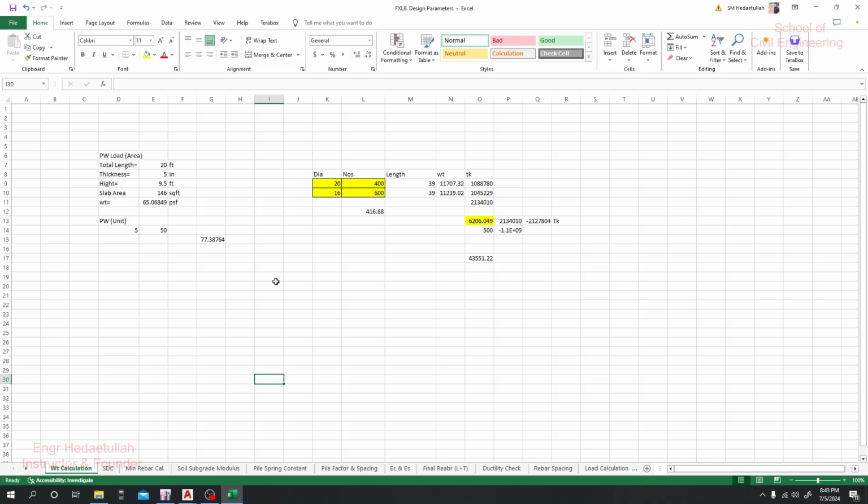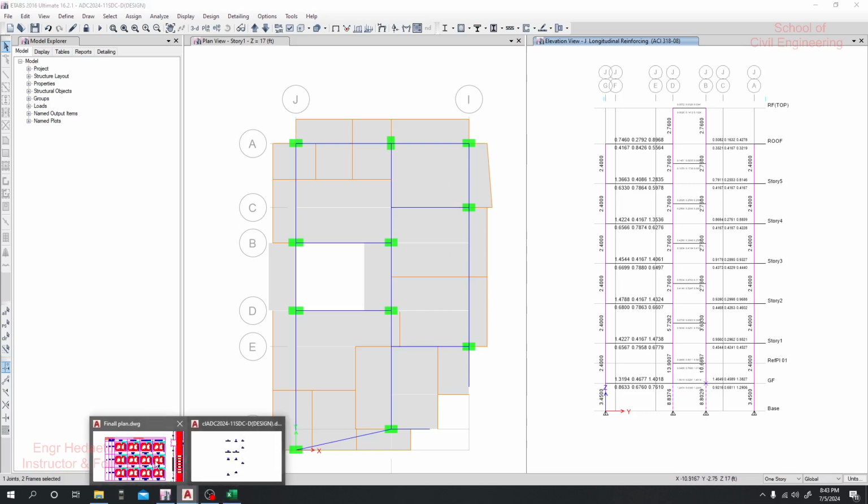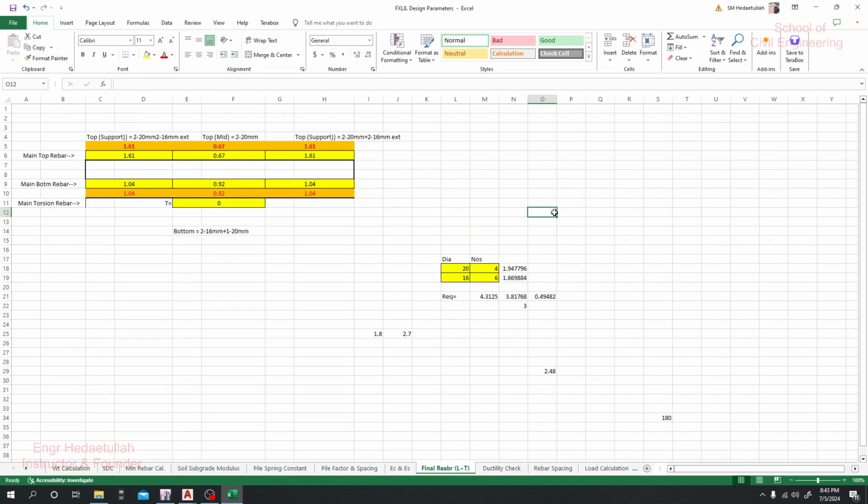So I always prefer 16 mm reinforcement in columns for those types of small structures. So I think it will be okay. So what I can do is go for, but in this case we're helpless, we have to use this type of arrangement. So now what we can do is go for this arrangement for our above column, not for below.